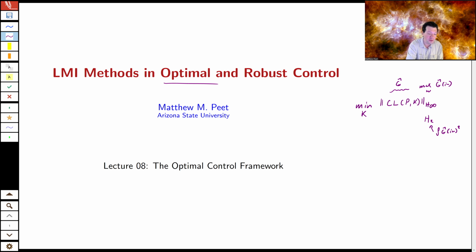However, we'll focus for the most part on the H infinity norm because that tells us something about the properties of the closed loop system which we're trying to minimize. Specifically, here's our closed loop system, and I'm going to label the signals W and Z for continuity. This tells us about the suppressive properties of this closed loop system from these exogenous inputs to our regulated outputs.